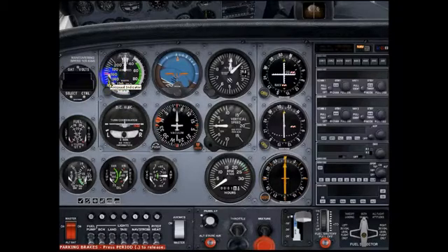that we'll talk about. All my private pilot people that are going to be taking the written exam or the computer test examination for the Federal Aviation Administration, you need to be familiar with these speeds. So white arc covers the flaps, green arc is the normal operating range, yellow arc is the caution speed range, and VNE, which is the never exceed speed.